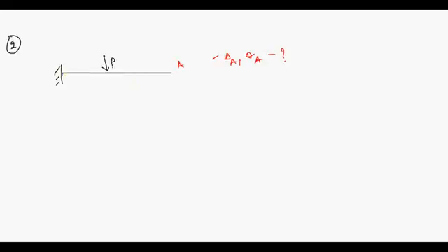It will deflect something like this. Okay, is it okay? Let me tell you one thing: up to this loading, the curve is going to be parabolic. After the loading, there is no loading on the span, so it will remain straight. So what I'm saying here is this much curve will be parabolic, and this much curve will remain straight. Is it okay?